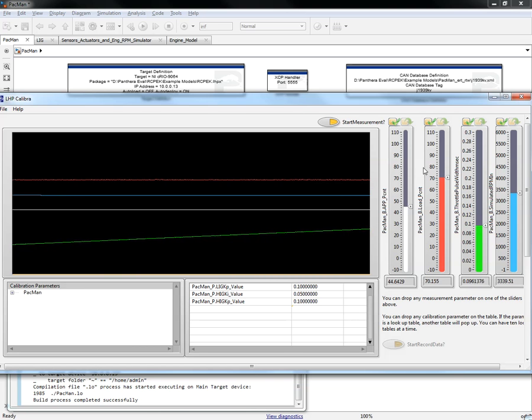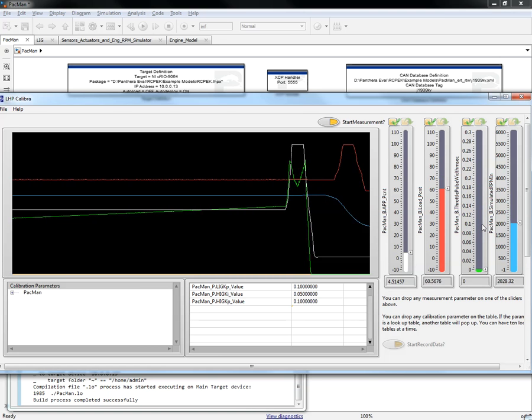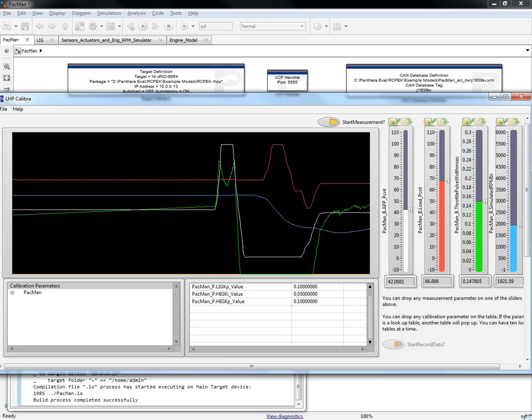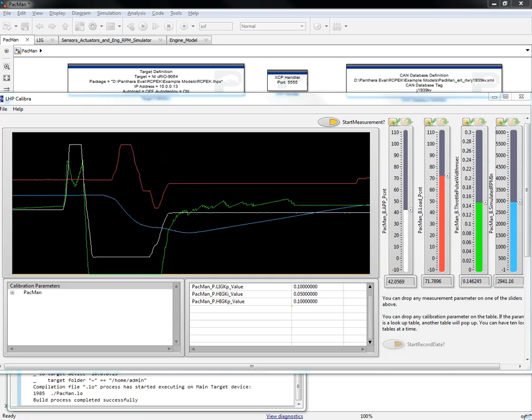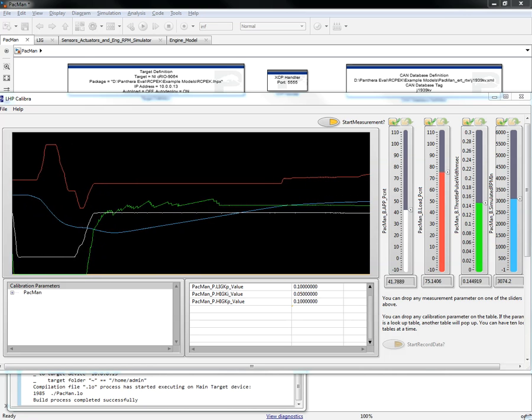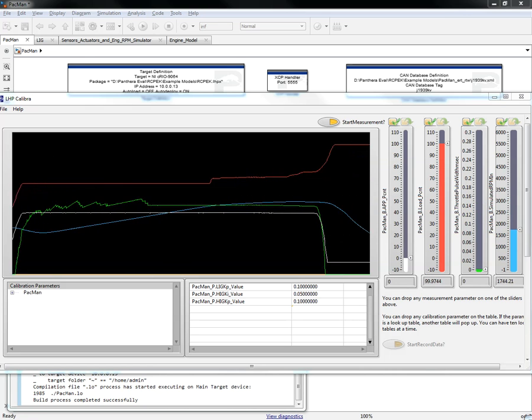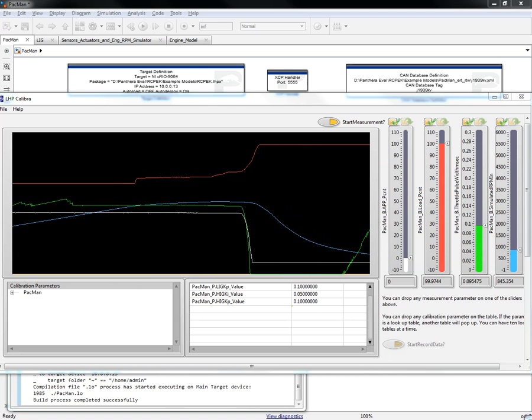So the 4 sliders that you see here are parameters that you are monitoring on the strip chart. In this case, the throttle input, the load input, the throttle valve command, and the engine speed. I can move those around and the control adapts and responds. I can also adjust the model and other control parameters by poking data into it.